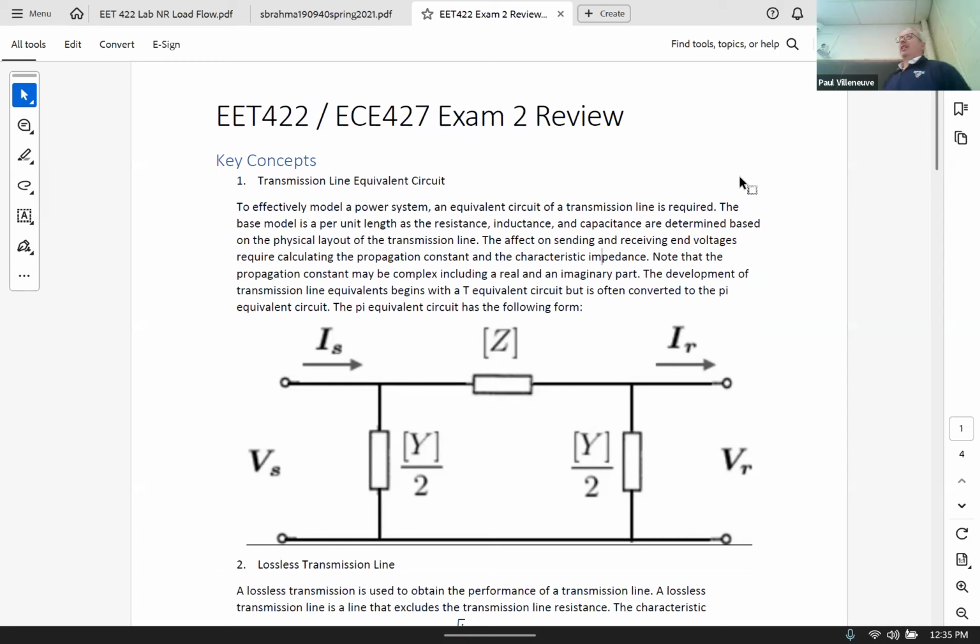And so we came up initially with the idea that any transmission line has some inductance, resistance, and some capacitance to ground. And we saw that that's not the best representation. It's usually much better to distribute the capacitance on either end of the line and then represent the Z in the middle. So just like the Greek letter pi, you have a sending end and a receiving end. The receiving end usually is what dictates the parameters, so normally that's your reference. And then the sending end has to be adjusted accordingly to deliver whatever is expected at the reference.